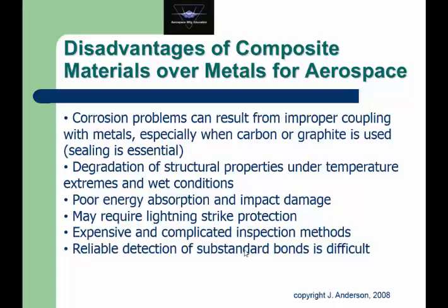When we lay up these plies of fabric for our composite material, for the stack up, if we end up getting a bubble in there or void, when the matrix material cures, that void still is in there.